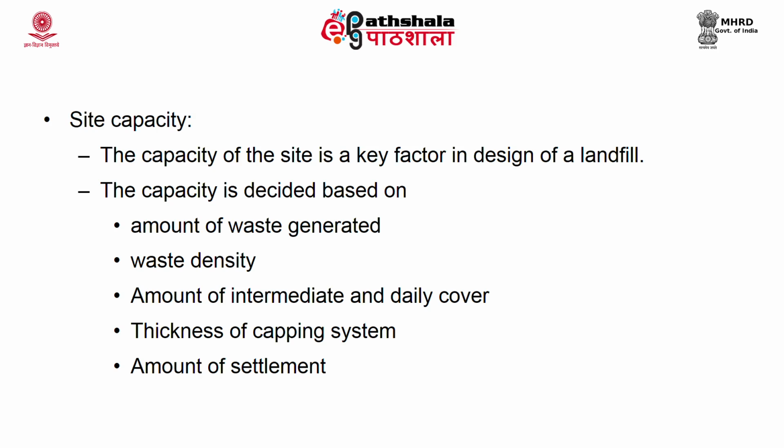One, the amount of waste which is generated determines your capacity. Your waste density also determines your capacity. For example, the waste will have different density. If you talk about the inert material, they will have a different density. If you have biodegradable material, they have different density. If you talk about the plastics, metals and all, they will have different density. So, the waste density also is an important parameter which determines the capacity of your landfill.